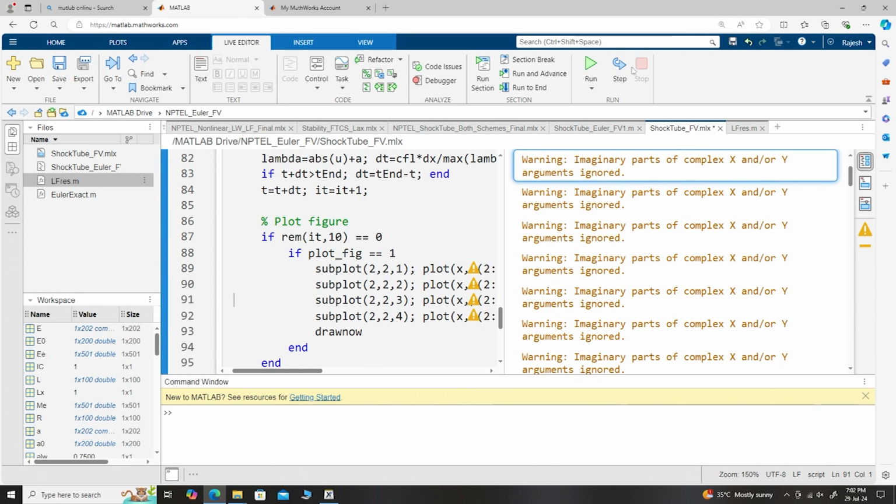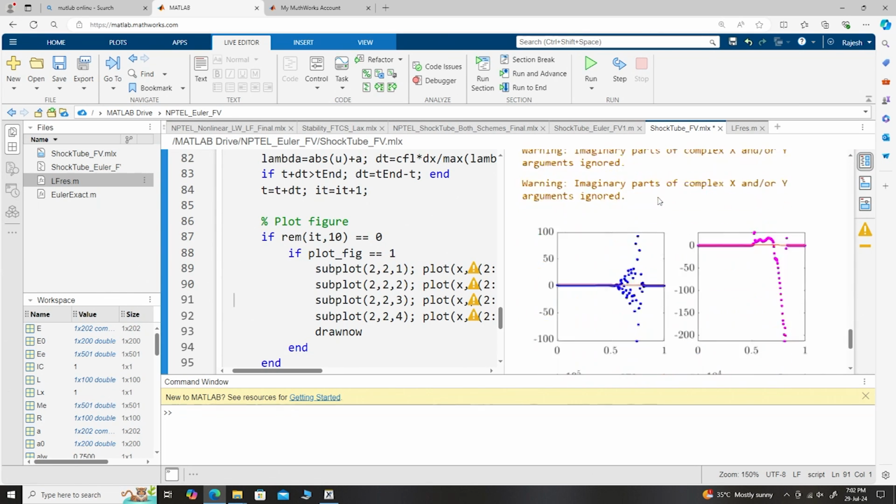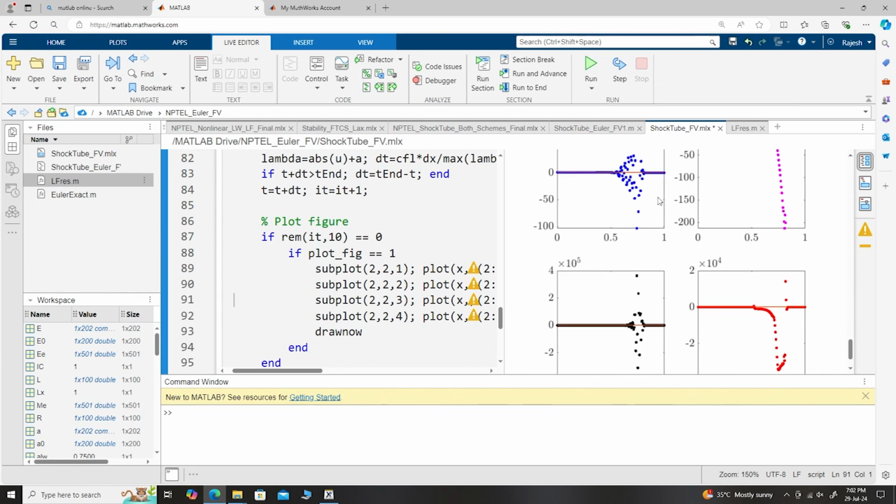Okay, so this is the issue we have. So, that is why the limiter is very important in finite volume coding. Although it is a very small part, you have to make sure that you are not overshooting or undershooting the maxima, local maxima and local minima, right.